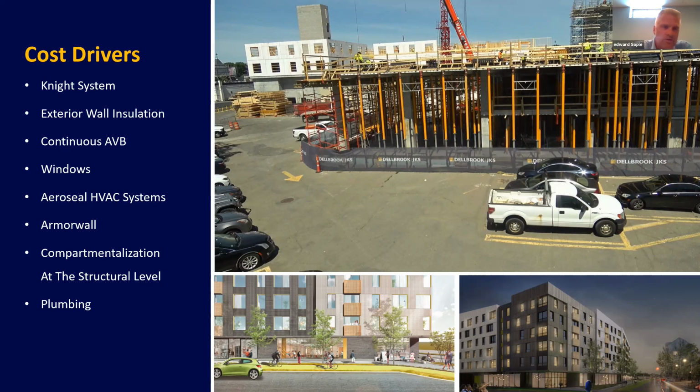The good thing about these windows, though, is they come with extension jambs, which is a cost savings versus having to block out or deal with the siding guy having to do difficult returns on the depths of these windows. The window suppliers are now getting better at having extruded trim pieces, which is helpful.